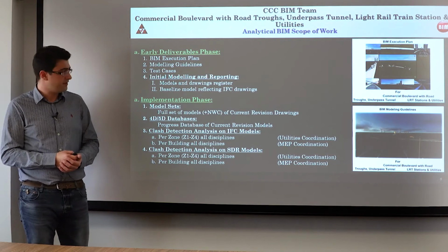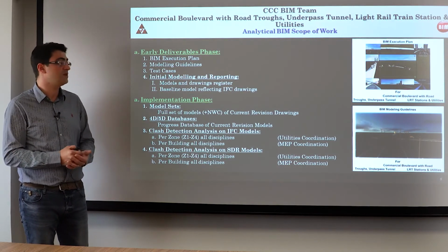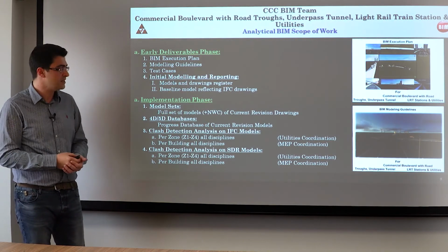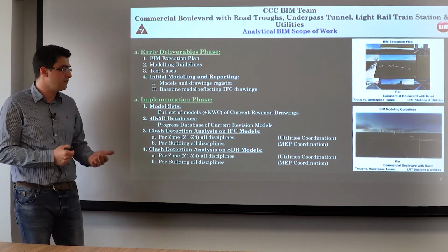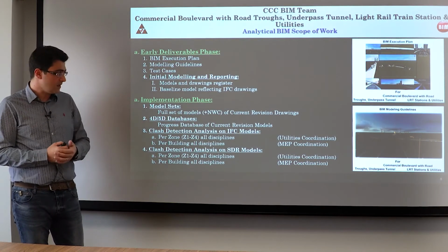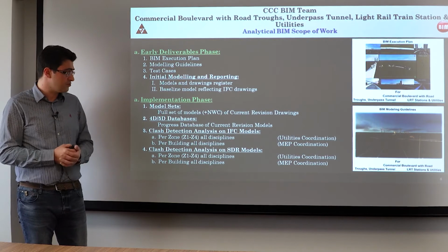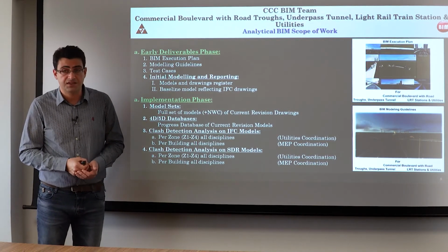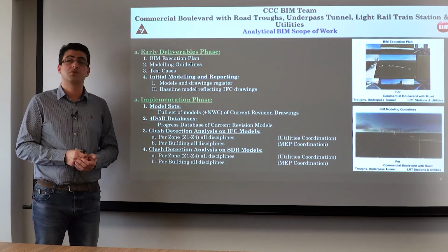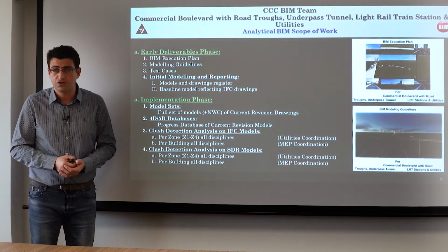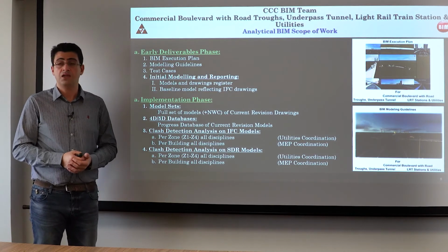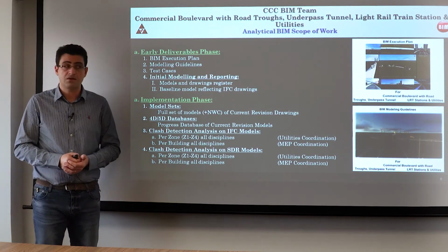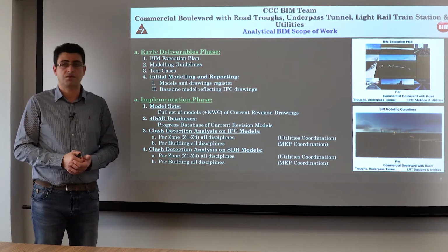In the implementation phase, we had to deliver model sets, full sets of the models, plus Navisworks and IFC extractions from the model. We had to deliver a 4D and 5D database, which means the model had to be linked with the schedules of the construction activities and with the BOQ elements, the cost of them and the quantity of them.